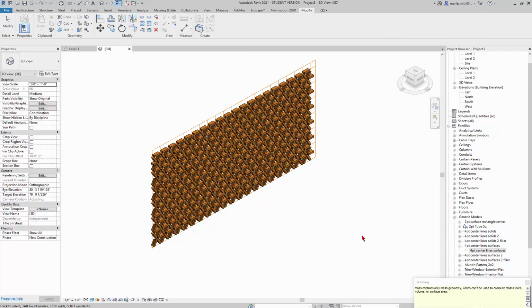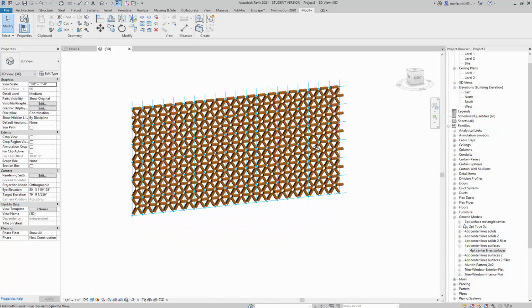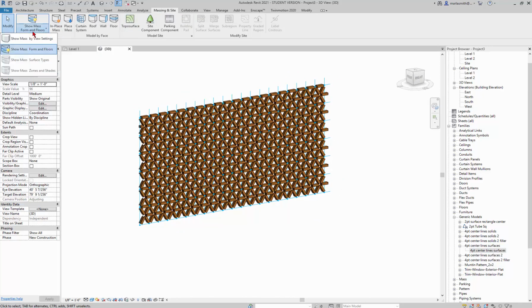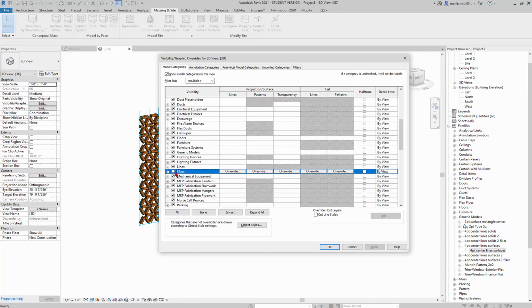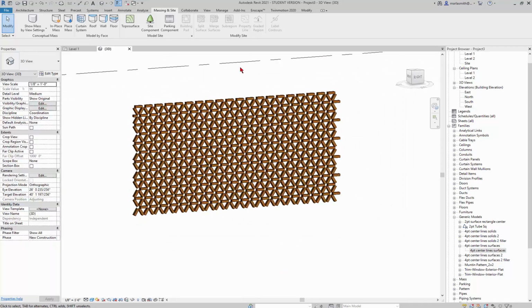And then if you don't want to see the background area here, this thing right there, you can turn the masses off. So the masses get turned off by either saying Show Mask by View Settings, right? Or sorry, yeah, Show Mask by View Settings. And it should turn them off. Or if you go to VV and double check that the masses are off here too, then that little thing won't show.